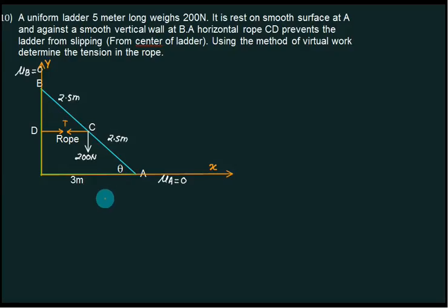My question to you is this: in virtual work we normally represent only the active forces. Active forces are those forces which contribute to work. If you ask me whether to show the normal reaction on this one, even if I show it, is it correct? This end is moving rightward, so is it a passive force? That is why I will not show this force.